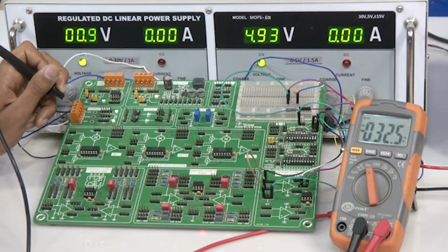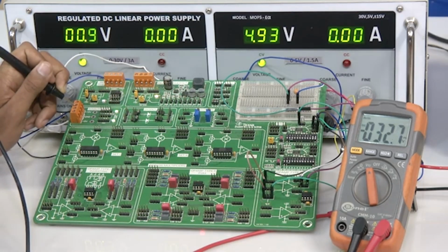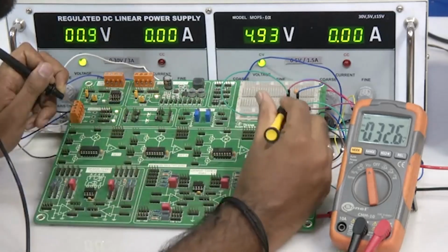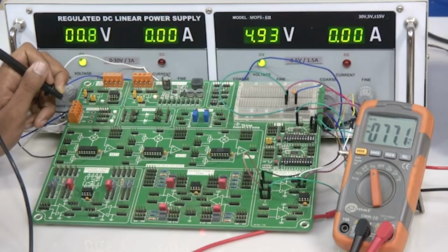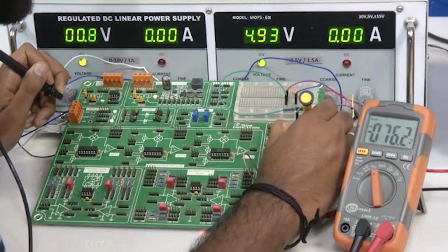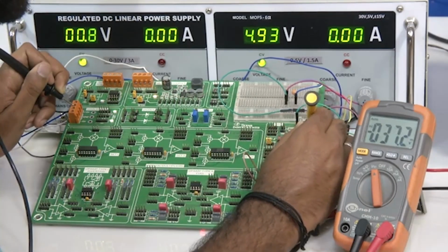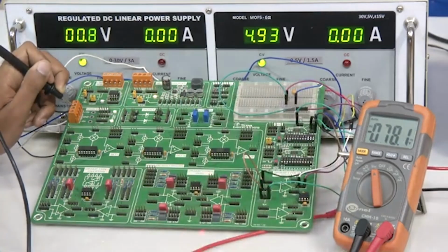So now we saw that by retaining the other two bits as high, by adding one more bit as high, we will get around 5 to 6 millivolt increase, correct. So this should go to around 37 to 38 millivolt when I change D2 to high. So let us see that. So we will change D2 to high. Okay. So now we have changed another bit, which is the D2 bit, correct. So we are getting 77.7, roughly 77 millivolt.